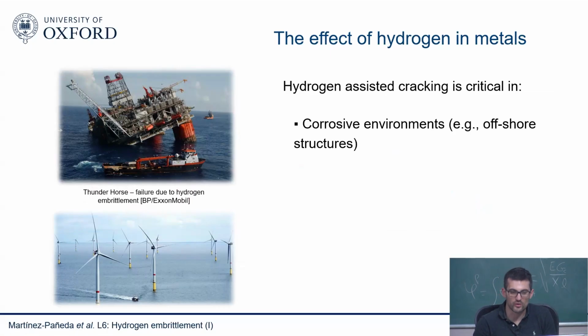So we have the situation where you have a lot of hydrogen coming from those corrosive environments. You have, for example, H2S environments in oil and gas. H2S is kind of a poison. So we discussed yesterday some hydrogen coming in from these electrochemical reactions. The poison will slow down some of those reactions, favoring the absorption of hydrogen into the metal. So in very aggressive environments, this has been a problem forever, and most of the efforts in the community were funded by oil and gas.